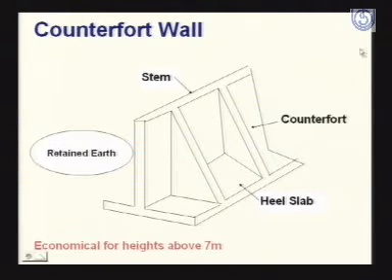What do these counterforts do? Let's see. As you can see from here, these counterforts are connected to the stem as well as to the heel, and they are provided at an interval of 1/3 to 1/2 of the height of the wall. So first of all, it is dividing the whole wall into different segments, and also it is providing support to the stem as well as to the heel.